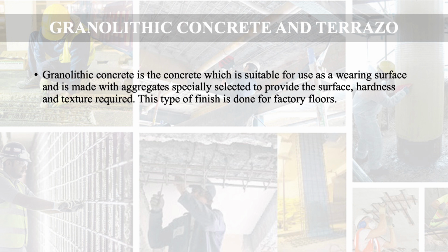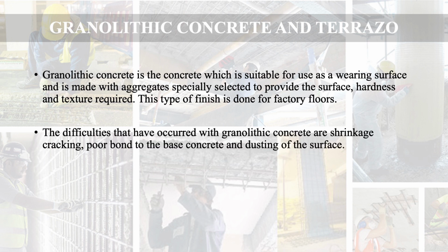Granolithic concrete is concrete which is suitable for use as a wearing surface and is made with aggregates especially selected to provide the surface hardness and texture required. This type of finish is done for factory floors. The difficulties that have occurred with granolithic concrete are shrinkage, cracking, poor bond to the base concrete, and dusting of the surface. These are the problems with granolithic concrete.